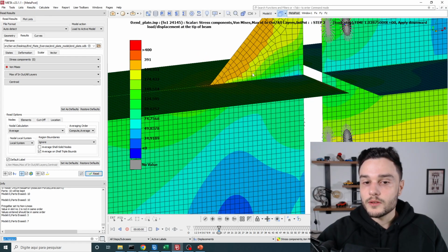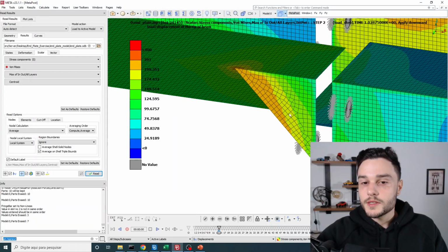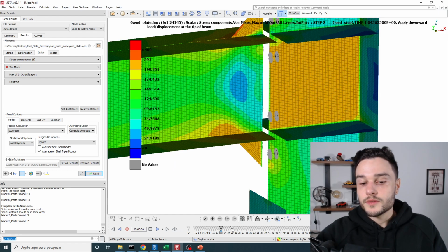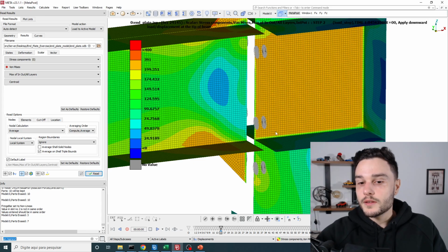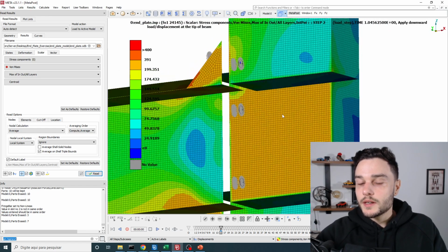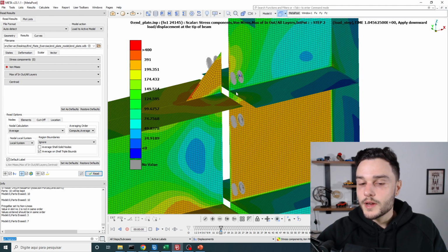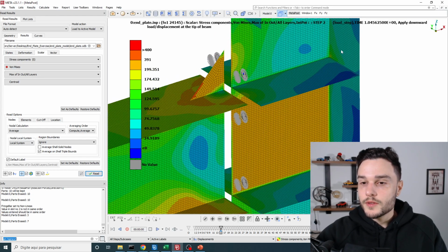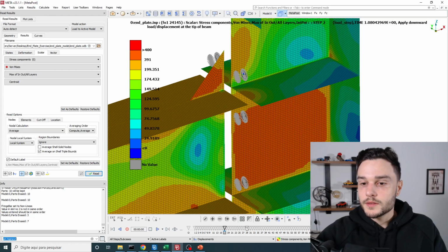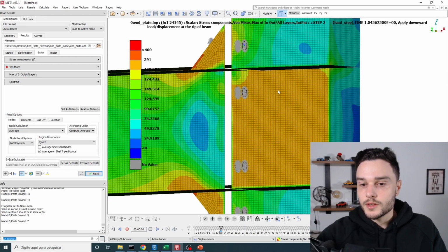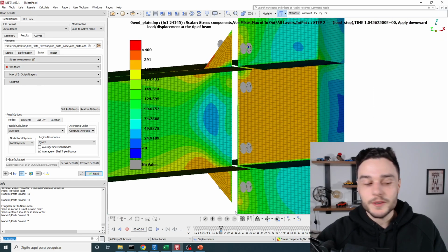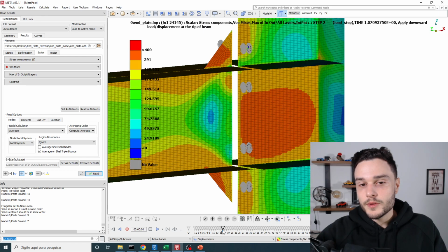And also here we have all this yielding and all this yielding. Let's continue. Oh, in this next one, everything in this region has yielded. So you see how important these stiffeners are, right? Because when we have this occurring, we lost all the stiffness in this region. So the forces are going to start increasing in the plates. Because, oh, sorry, this orange was not yet related to yielding. It is this darker orange. So let's disregard everything that I have said. But the rationale is going to be the same.